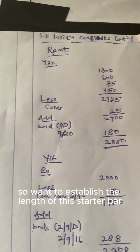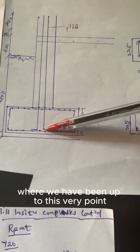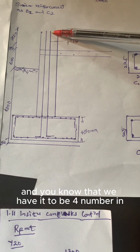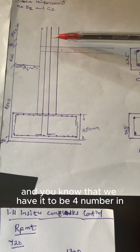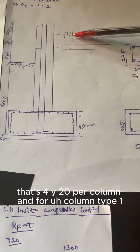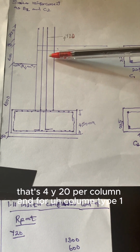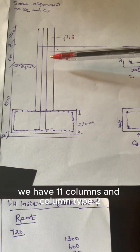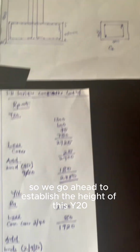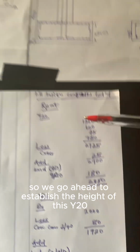So we want to establish the length of this starter bar from this point where we have bend up to this very point. And you know that we have it to be 4 numbered in a column. That's 4y20 per column. And for column type 1, we have 11 columns, and column type 2, we have 4 columns. So we go ahead to establish the height of this y20.